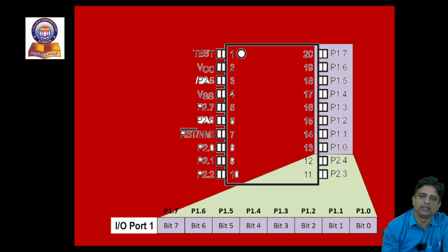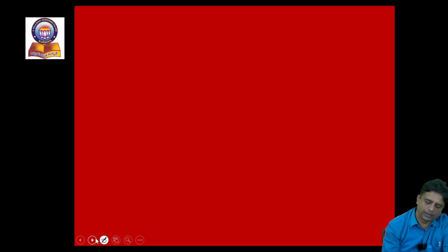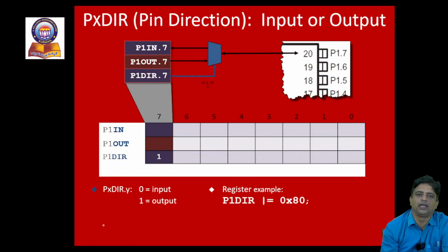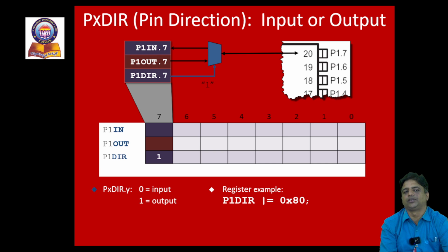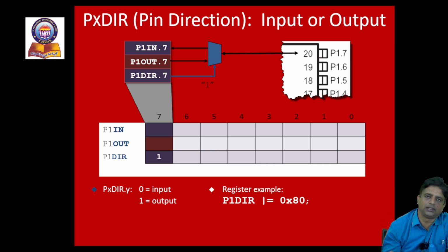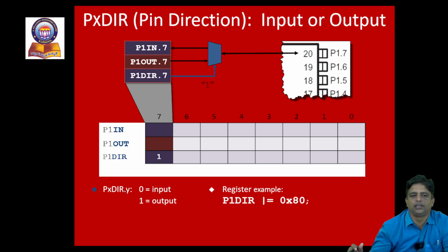Each port pin, for example of port 1, is shown in a register arrangement. If we want to access P1.0, there is a position internally buffered to this pin. If we want to access P1.7, there is a position inside the device mentioned for buffering the operations. So what are the operations we have to do before selecting the port? There will be some support registers internally which will help the port to be addressed either as input or output.